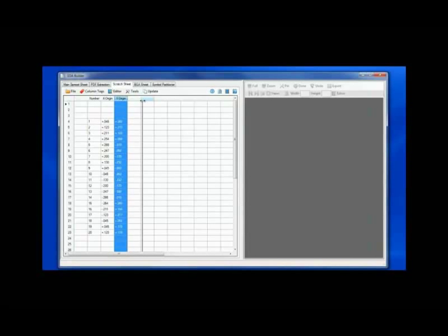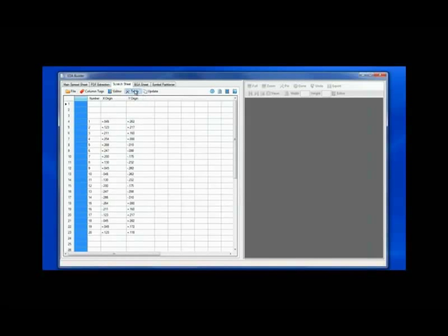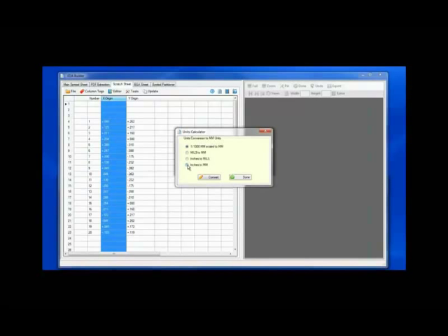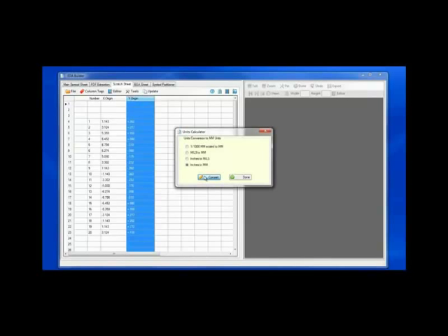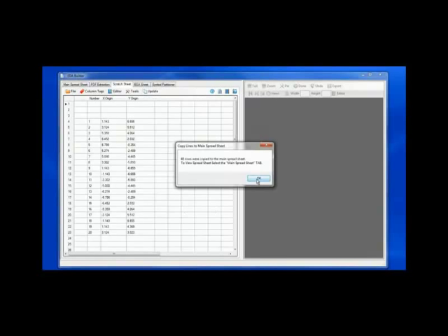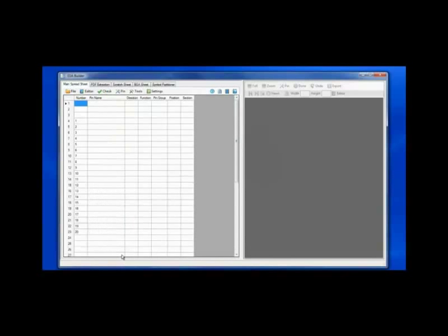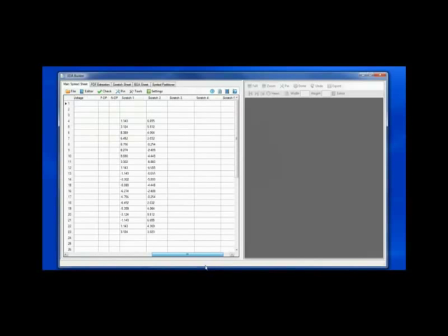And then I will scale the units, in this particular case, from inches using the scale units command to the particular units that I will be modeling the part in, in this case millimeters. Once the scaling is complete, I can then transfer the content to the main spreadsheet using the copy tag content, which I will later use to model the schematic symbol model. And I will also use this datasheet to model the PCB footprint.